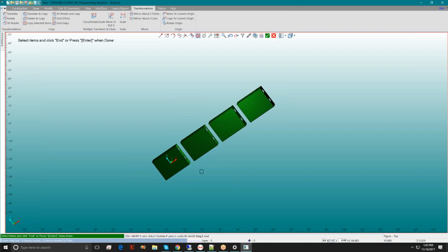If I do it another way, if I go the opposite way out, from the top right to the bottom left, as long as it's inside or one of those lines touches the box, it will select them. So for multiple selecting, you either want to use the window one, or the inside out window where the corners cross over. So that's how we can do multiple selections.